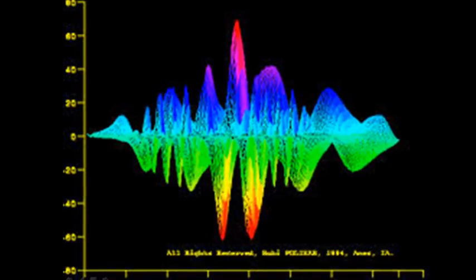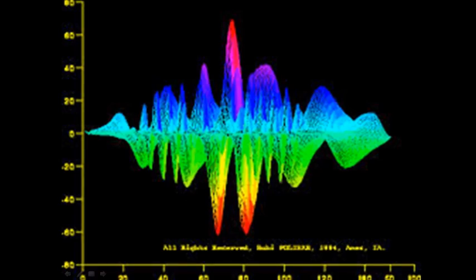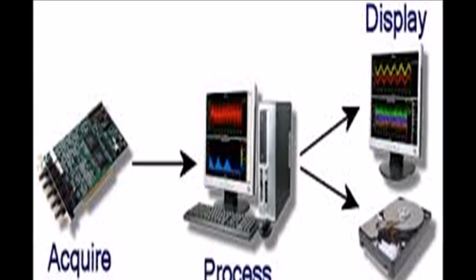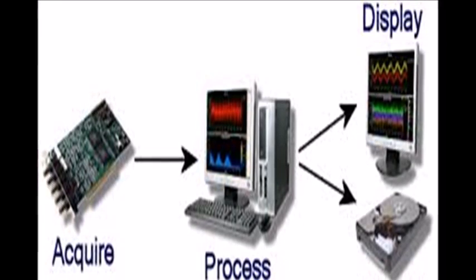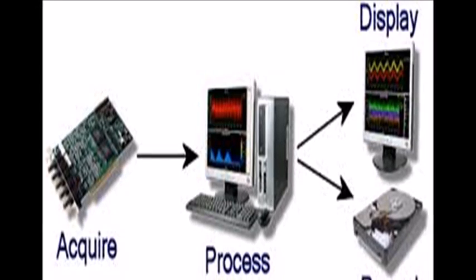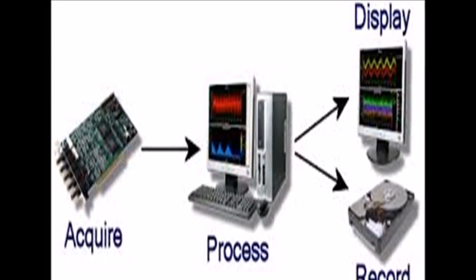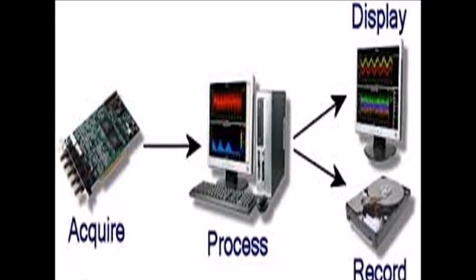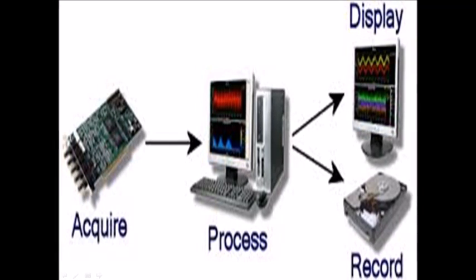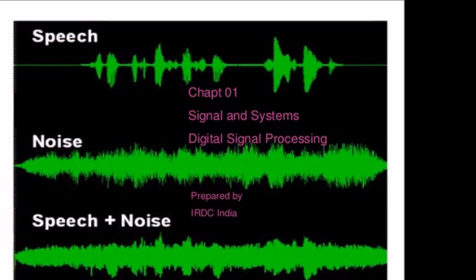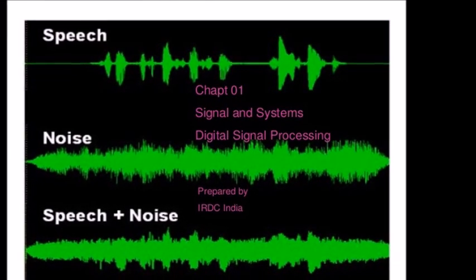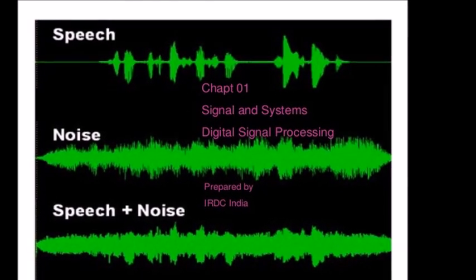argument is the phase. Using Fourier analysis, representing a real valued signal as a sum of periodic functions is often written as complex valued functions of the form f(t) = z e^(iωt), where ω represents the angular frequency and the complex number z encodes the phase and amplitude.